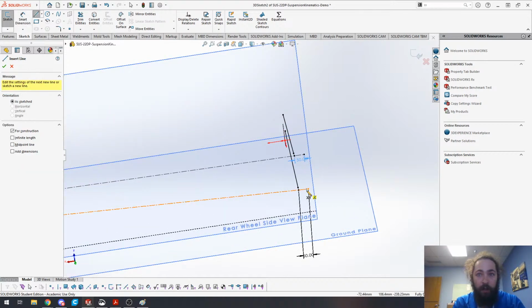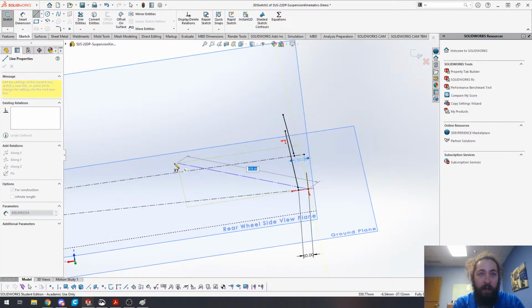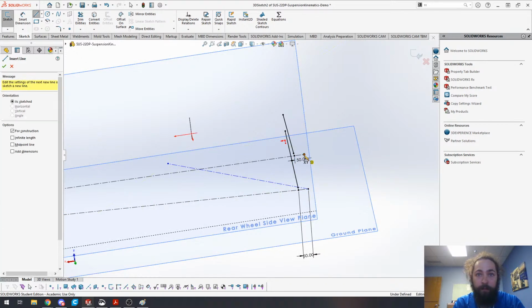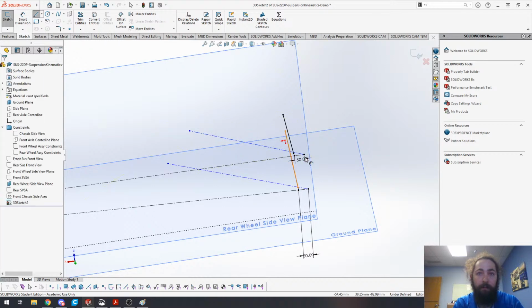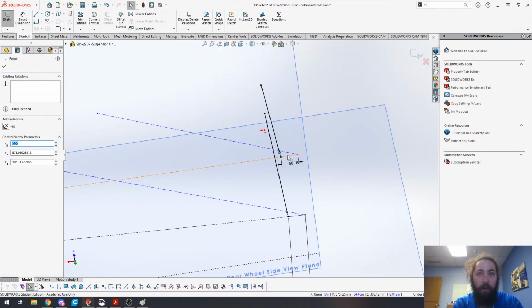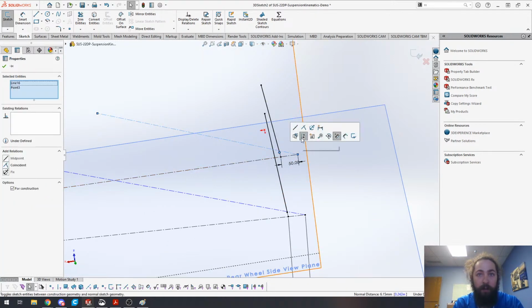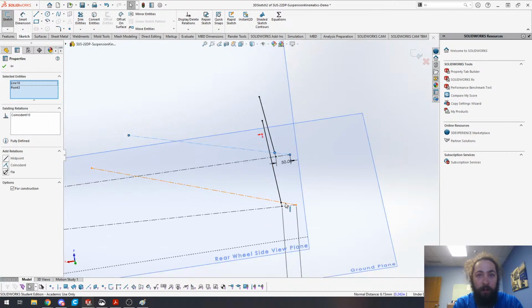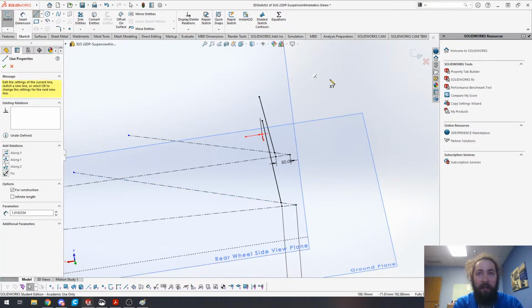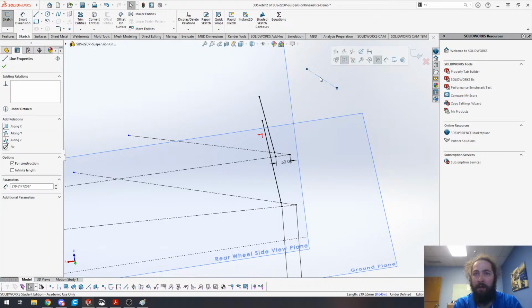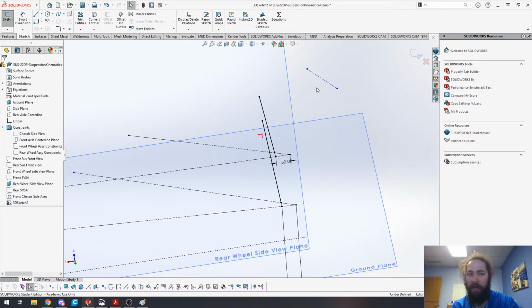So we'll start on XY here. Cool. And then we'll make those two coincident. One of the other things I want to point out is as you're starting to make these lines, it doesn't actually make it, like I just made a line in the XY planar direction, but it doesn't actually constrain it to that.